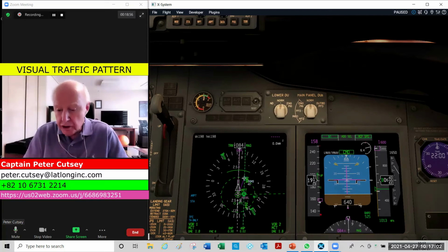There we are. So I'm going to go ahead and release the aircraft, and we'll do those 4 functions. We'll try to get them all done. That is flaps 5 as we're pitching down to 10 degrees. Well, the autopilot's going to do that for us. And start the turn to heading 264 degrees and thrust coming back. A continuous thrust reduction to maintain flaps 5 speed. Let's see how it works out.